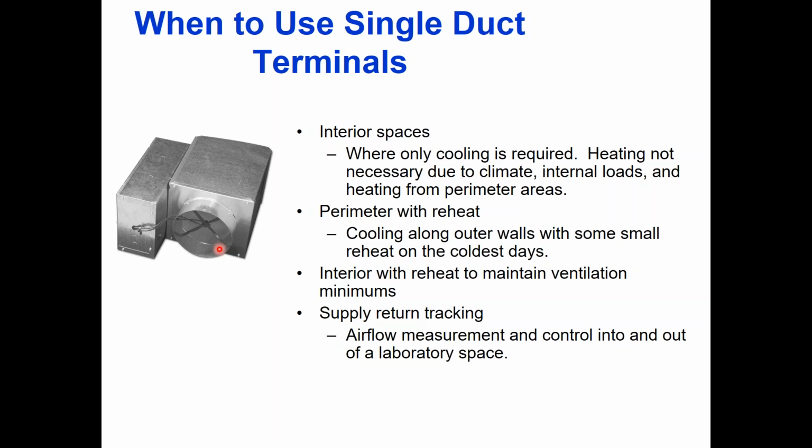So why do I need any heat, right? Unless I have a freakish amount of outside air coming into that zone. Everything in my interior zones is based on the interior loads and has nothing to do with weather. So there is not going to be any heater on here. So that's when you're going to use these single duct boxes. You can add a reheat to them.